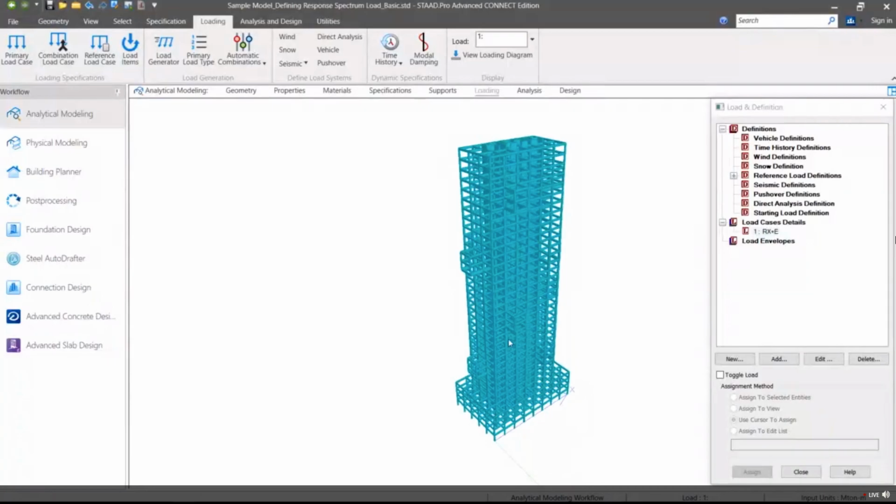In the output, the details of each irregularity check are mentioned. For torsional irregularity, first the displacement of each diaphragm in x and z directions are mentioned, and then the ratio is printed. It is compared with 1.2 and 1.4, which are the limits, and the status is mentioned in the table for each diaphragm. For this model, there is no torsional irregularity noticed and all diaphragms are okay.